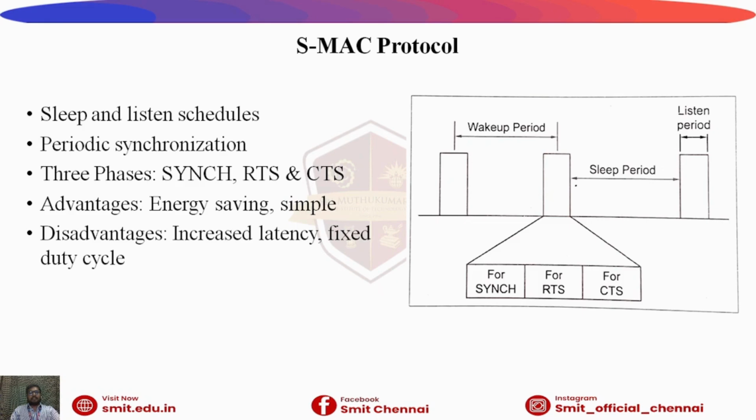SMAC protocol. It is the short form of Sensor MAC protocol. It is one of the earliest MAC protocols designed for wireless sensor networks. Key features are that nodes follow periodic sleep and listen schedules, and neighboring nodes synchronize schedules. It has three phases: sync phase, RTS phase, CTS phase. In the sync phase, nodes exchange schedules.